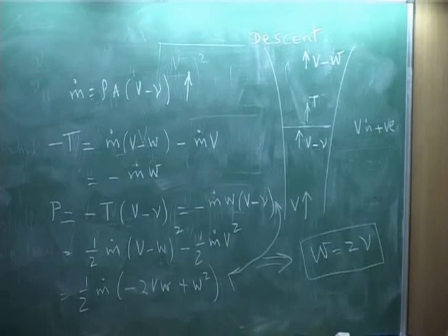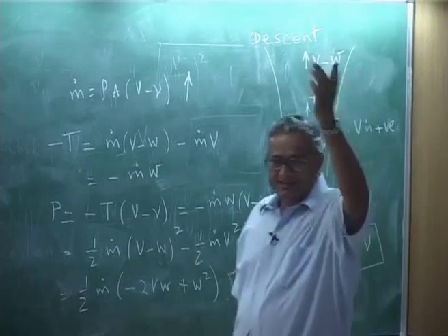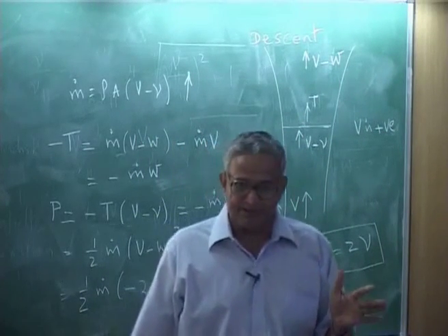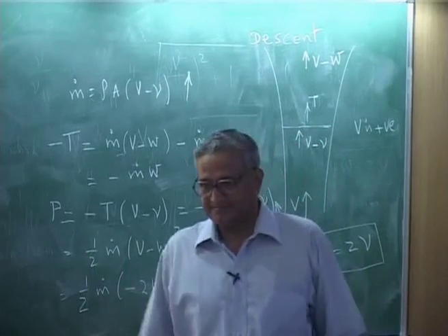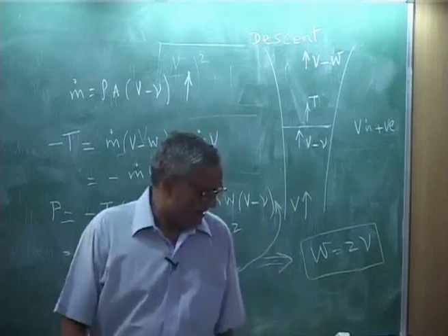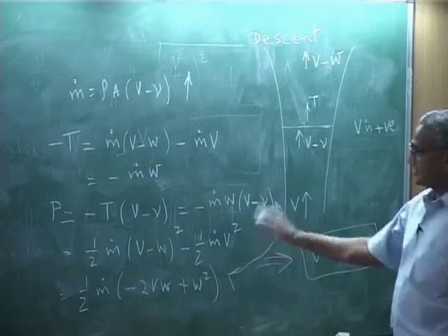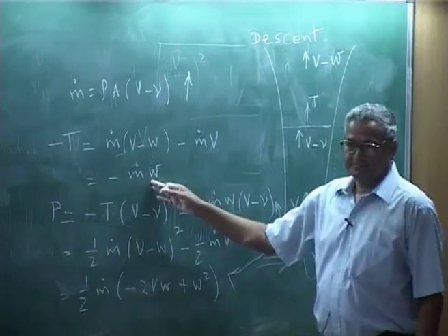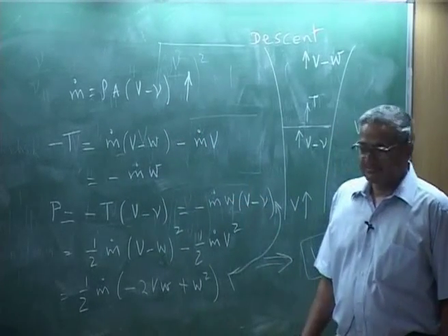So, whether it is up, down, hover, does not matter. The far field induced velocity due to the rotor disc is actually double of what happens at the rotor disc. Now, you look at your thrust, because you got this expression. I will be substituting this quantity here.